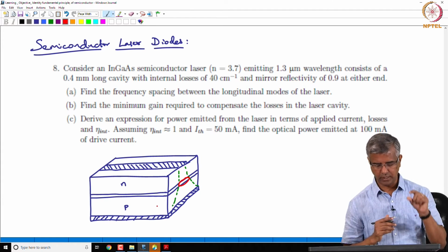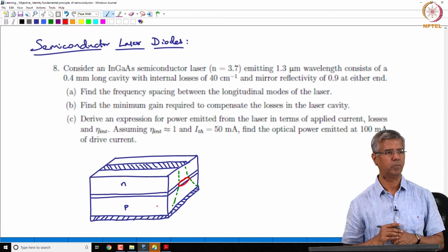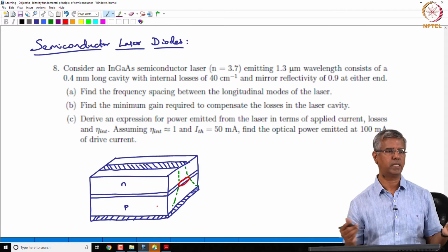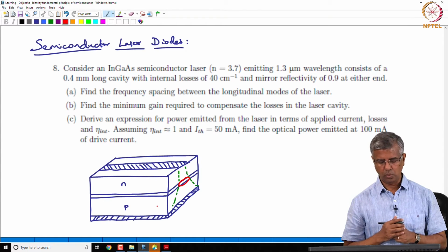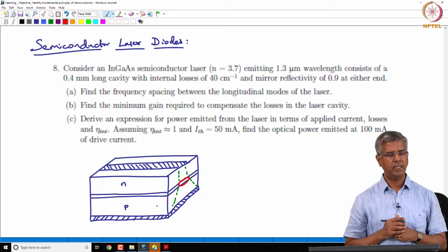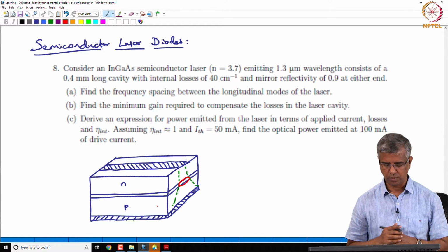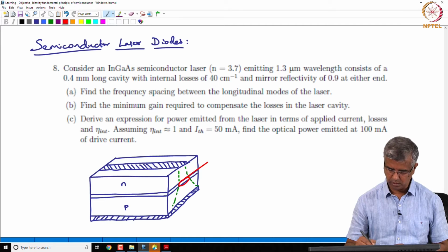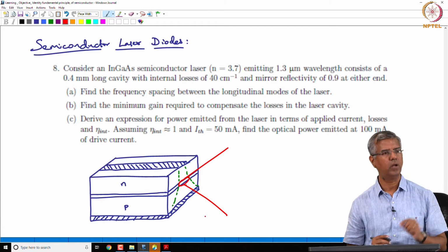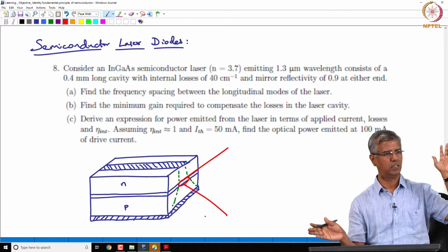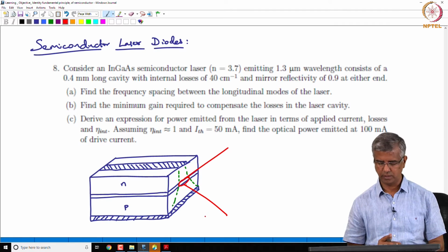The vertical thickness could be in the order of a micron, but on the horizontal side there is not as much of a constraint. So, when you look at the light that is emitted from this structure, the light emitted in the vertical direction, since it is coming from a smaller aperture, tends to diverge much more.